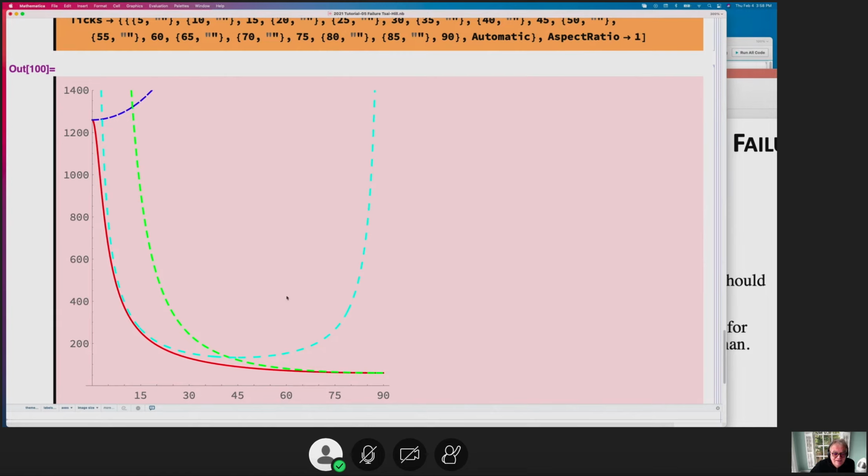These lines say you're not going to fail if you have 75 degrees. You're not going to fail the specimen in shear until you reach this. But you're going to fail due to transverse direction here, which agrees with Tsai-Hill. At about 45 degrees here, max shear stress says you won't fail until here.